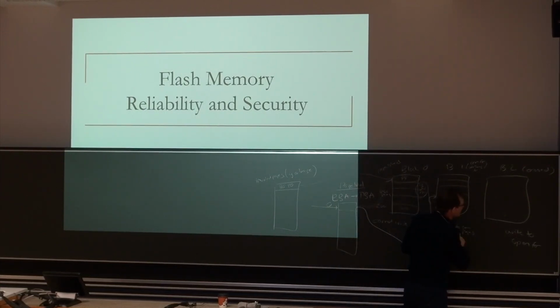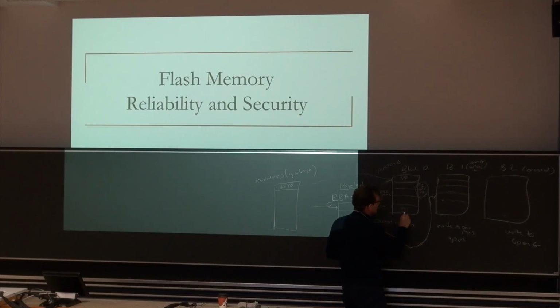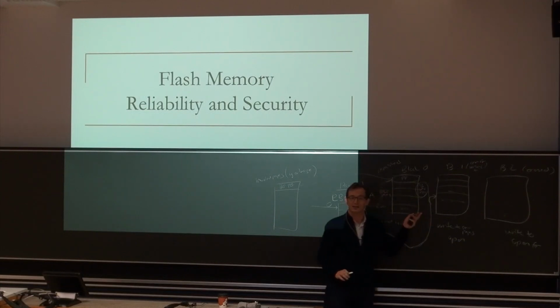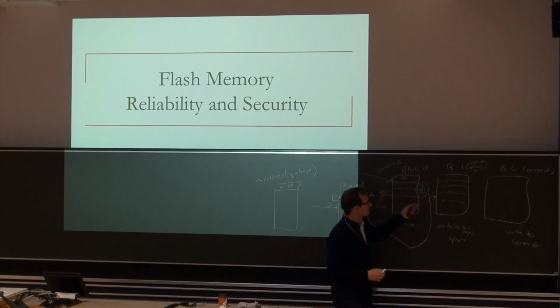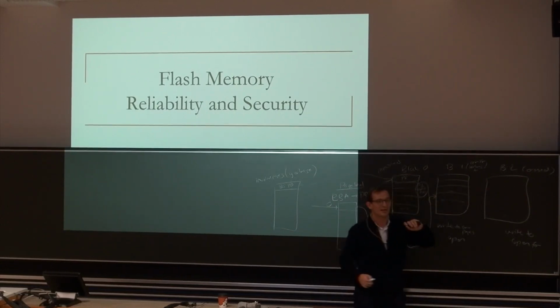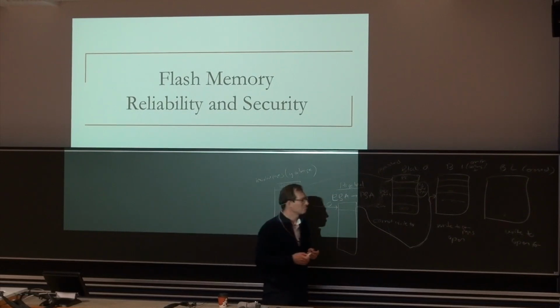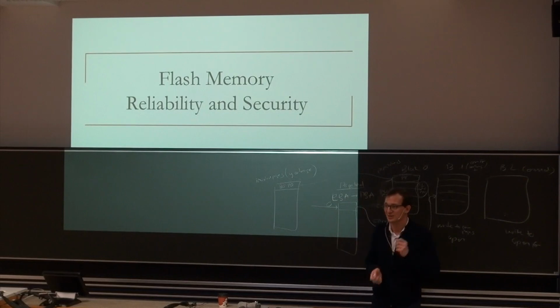Maybe it's better to level this wear out across the blocks somehow, such that you level the number of writes across the blocks. The question is, how do you do that while also trying to minimize the garbage that you have? That's why the design of the controller is actually a very complex design, because these things actually go against each other.